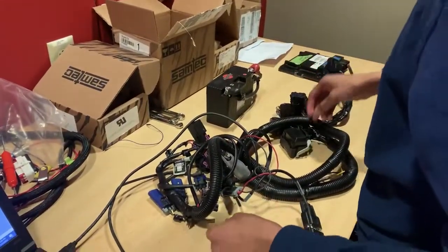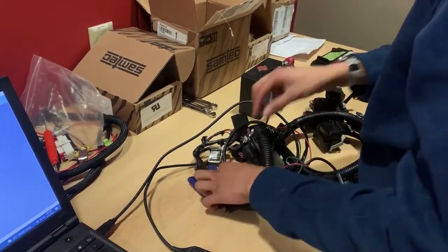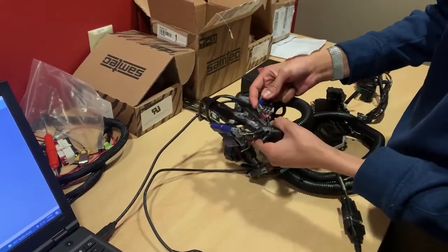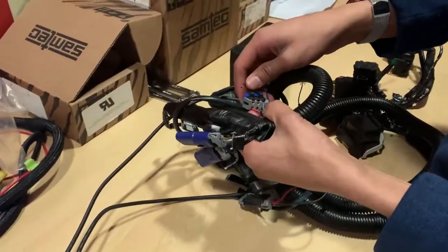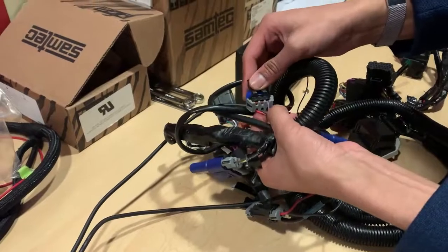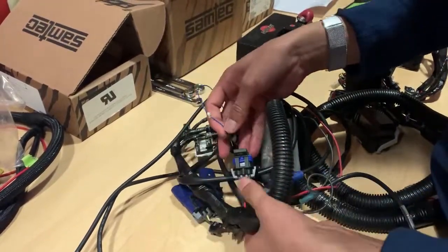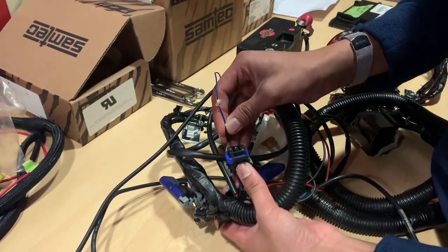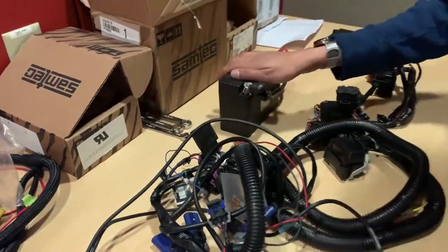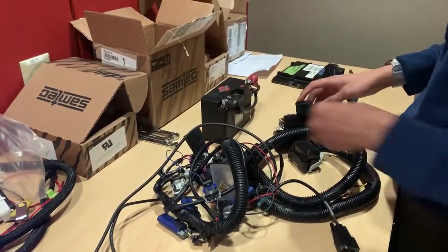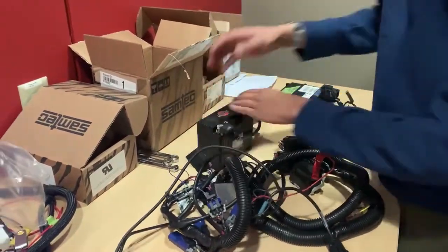You're also going to need the ECU key. So here's this one right here with the purple, black, and red. This is the key switch. So to turn on, you're going to jump the red to the purple wire. So we're just going to stick this in right here for now. So we'll just stick it in the hot side. And then for power, you can use a power supply. Over here, just for portability, we have the battery, so we'll plug the ECU in first.